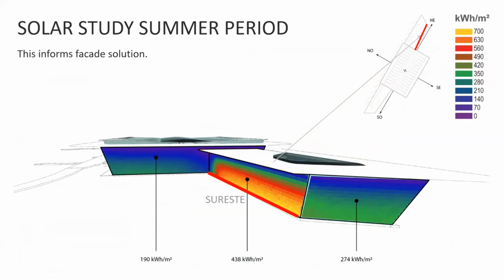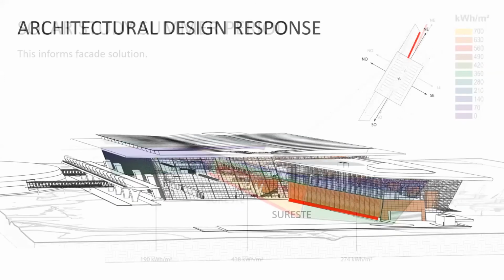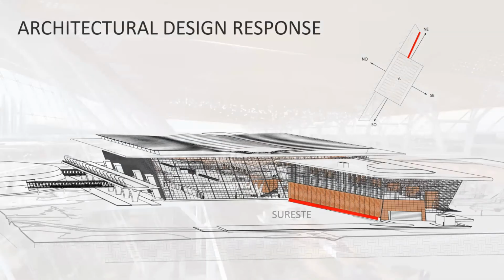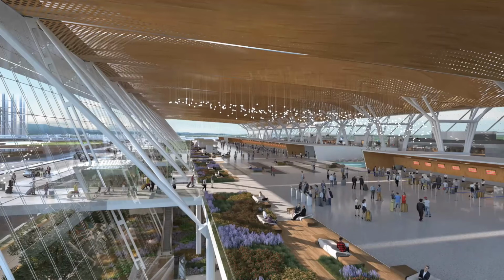Looking at the envelope also, we did studies of all the envelope just to understand how to shade it, how to control that transparency. We found issues like this one in which we're getting more solar gain. And then we added what you see here in the bottom right, we added more solar protection, those critical areas that we found. Again, looking envelope by envelope, trying to improve it and to respond to the conditions of that specific location and orientation.